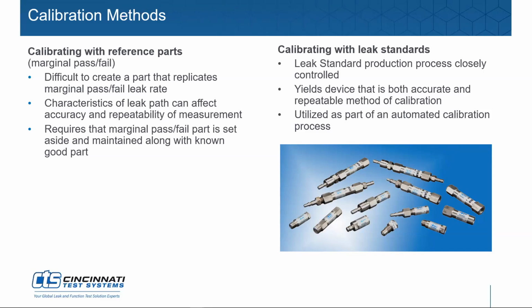Well, what did we say? Flow rates through parts are not repeatable. And what you want to use as your calibrated part is a non-leaking part with a known flow rate in it, a manufactured leak standard that is designed to flow repeatably test after test.